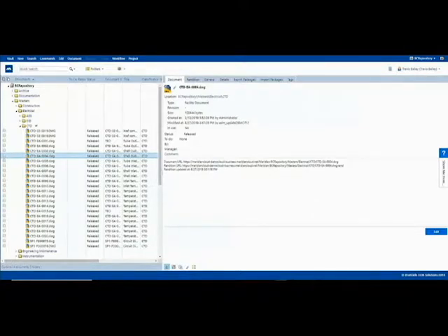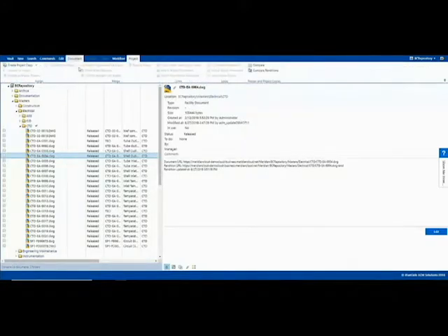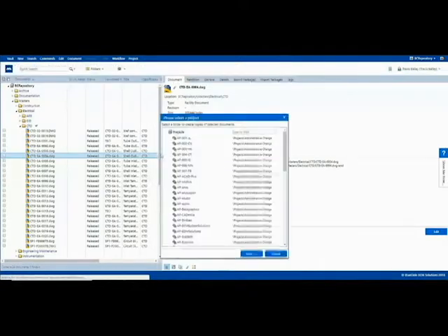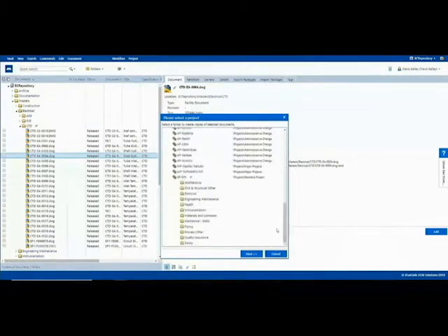After reviewing the circuit diagram on the comments and markups, we decided we need to route this document for change. But first, we need to create a project copy. You simply click the drawing. I can right-click or go to Project, select Project Copy. It's going to ask me which project it goes to. I'm going to select SP1. It's automatically going to file it for me.